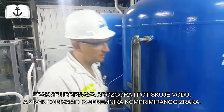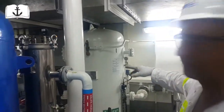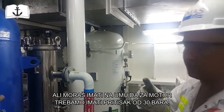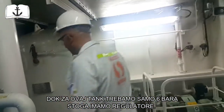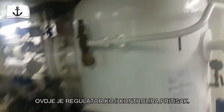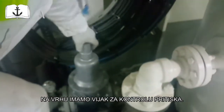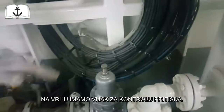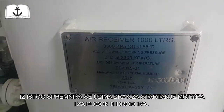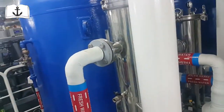Okay, where is the air coming from? From the line, from the bottle. From that bottle. Yes, but you have to remember that for starting the engines you have 30 bar air. For these purposes you have 6 bar. But it's coming from the same one? Yes, but you have the reducer for regulation. Okay. Here is the reducer. You can show. On the top there is a regulation bolt, and you can adjust the pressure to what we need. So the same air receiver which you use for starting the engine, you are using it to give pressure to the hydrophore, or also to the general purpose connection.